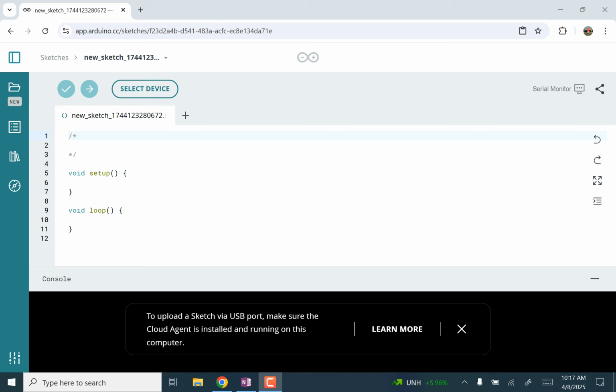When you open this programming environment, you see two things already set up. One is setup, and that's where we're going to define which pins we're going to be looking for values from. Those are our inputs. And which pins we want to set values to and say, okay, this one's 5 volts now, this one's 0 now. Those are the outputs, okay? Then after we've set that up, we've defined the layout of the pins.